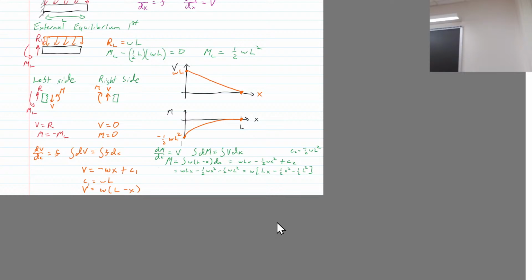If we're looking at that face, it's a little bit confusing because if you scroll down to the next slide, we say these are the contributions from PY, and this is going to be tau xy. That's also a little bit confusing. So we're looking at the x. If you draw this, tau xy should be positive, the x is coming out of the beam. So yes, tau V is contributing positive tau xy. Tau T, as we're calling it, is contributing minus.